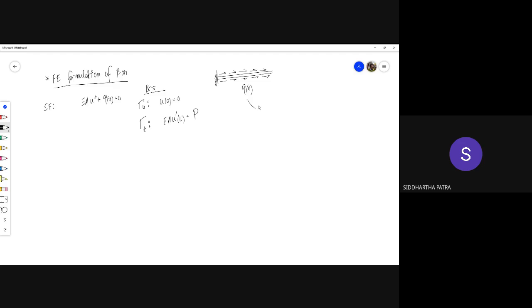This one has kind of this unit, and then you are applying at the free end this concentrated force P. So we showed that in two ways we can arrive at that equation, either from the potential energy statement or by using Newton's method, where we would draw the free body diagram at the boundary as well as at an arbitrary x location. So x is the coordinate along the bar,